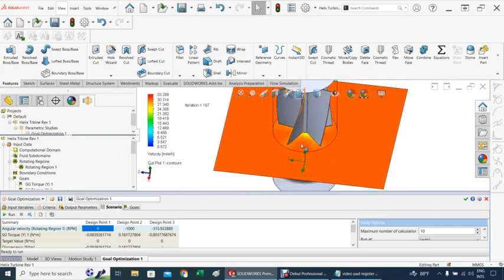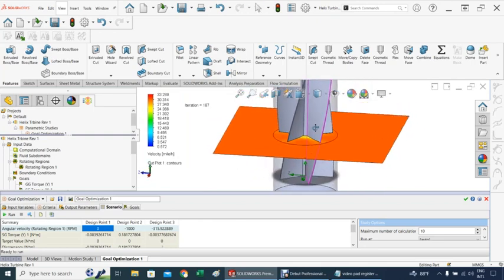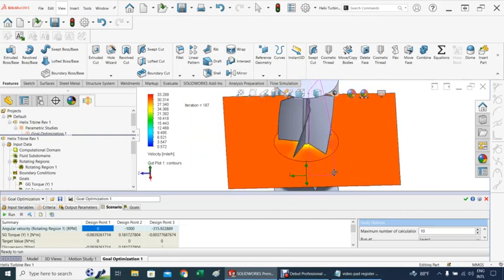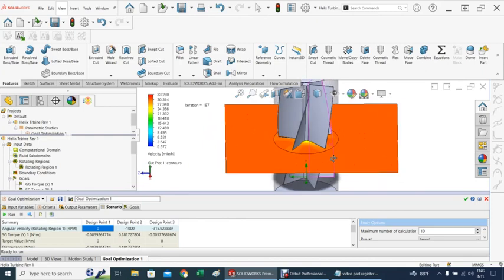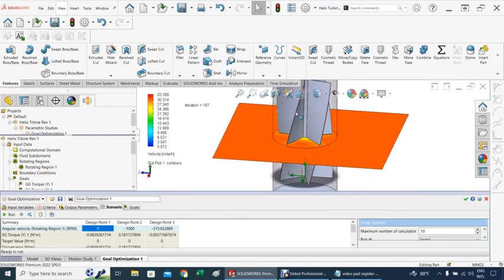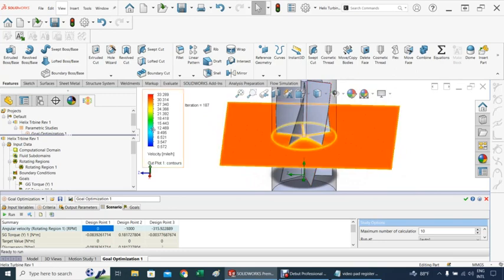Too much red here, meaning that I'm at the maximum velocity and it's a waste of energy, at least at that position. I don't think it will change much at the top. So this turbine is wasting a lot of energy. So I need to perhaps twist it more. We'll see. Now, the minimum seems like it's around, I don't see any green here. So I can definitely improve this.